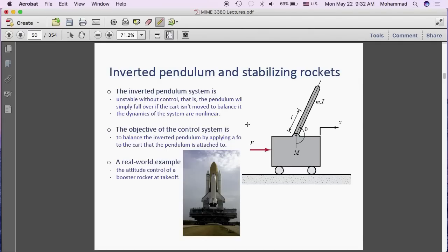And it looks like a pendulum around theta equals pi. It's a pendulum about the unstable equilibrium. So you have to counter the motion to keep it at the vertical position. So that's what is called an inverted pendulum. And it's a very interesting control problem.